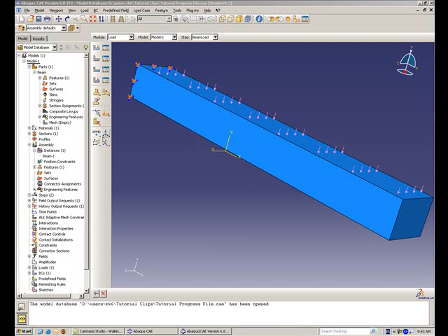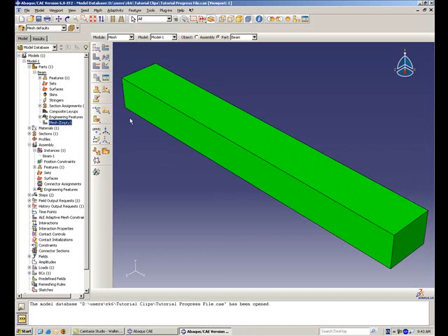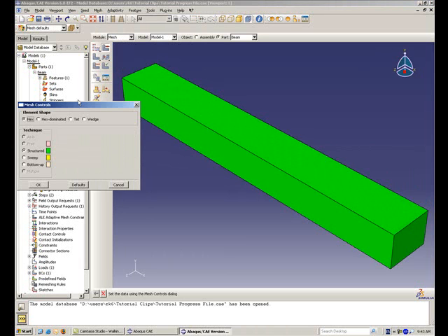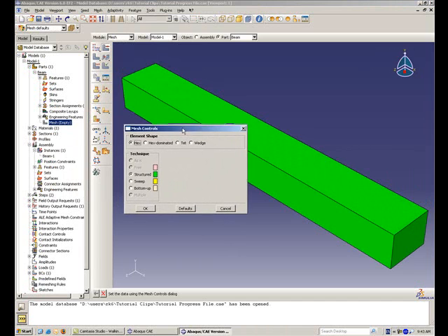The final step before starting the analysis is meshing the part. Start the process by expanding the Parts and Beams branches of the model tree, then double-clicking on the mesh container. Abaqus automatically switches to the Mesh module. From the main menu bar at the top of the screen, select Mesh and then Controls. Accept Hex and Structured as the default element shape and technique selections.